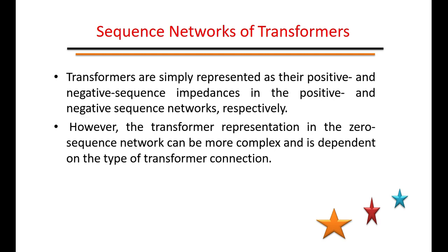If you are using three single-phase transformers for three-phase use, or even a three-phase transformer, they may be connected in star-star, star-delta, delta-star, star grounded, without grounding, and so on. The zero sequence path depends upon the grounding of the transformer. Therefore, for different types of transformer connection, the zero sequence will differ. However, in the positive and negative sequence, it is represented by its respective positive and negative sequence reactance.